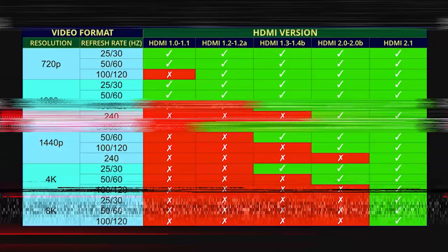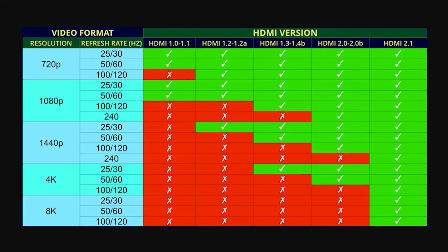However, don't forget that sometimes using adapters may impose certain limitations on functions, resolution, or certain features which are only available as long as original HDMI cables of a proper type are used. That is why we recommend using compatible HDMI cables of the type natively supported by your devices, so that you always get the best possible quality of images and sound. All HDMI versions are compatible with DVI as long as you have an adapter. However, DVI will only transmit video, but no sound.